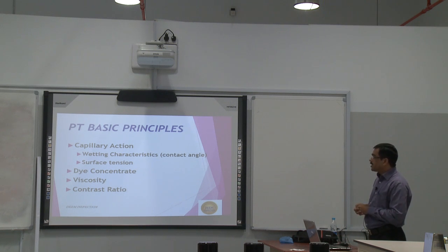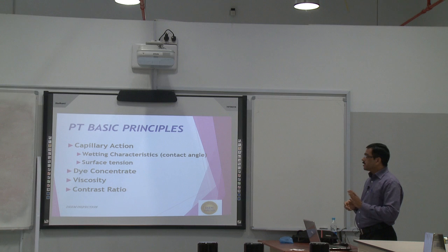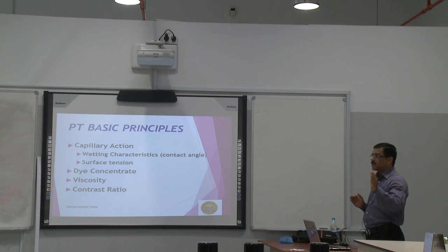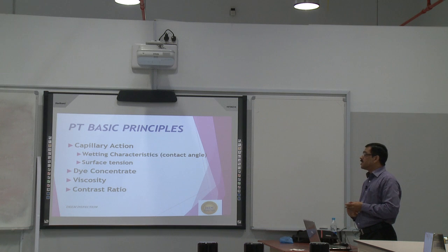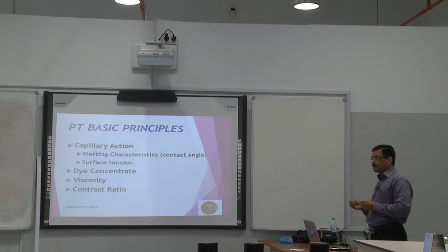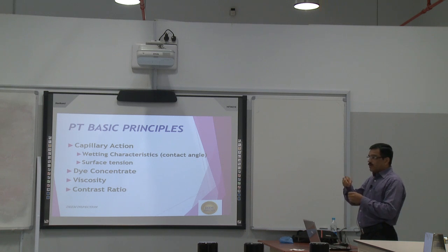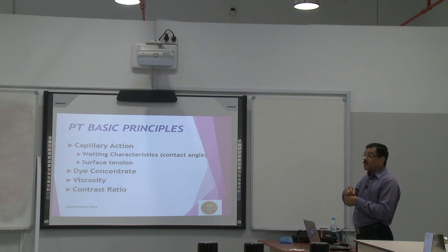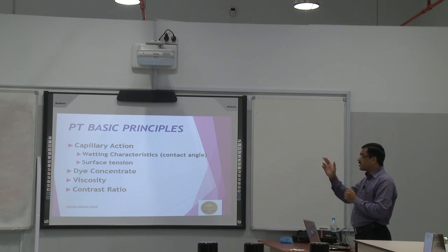Some basic principles of this PT: the first one is capillary action. Penetrant testing works on the basic principle of capillary action. What does capillary action mean? Any liquid has a tendency to enter into defects and openings. It can enter or climb. That tendency is called capillary action.